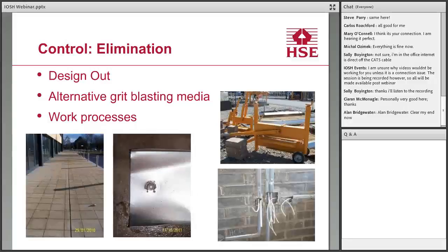In the middle is shot firing. That's an alternative to drilling. On the right-hand side is a block splitter, so that takes away the need for using cut-off saws. It's quick, there's no noise, there's no vibration, there's no dust, so it's a really simple solution. And in the bottom right-hand corner is an example of where they haven't chased out. What they've done is overcovered the cables prior to boarding, and all they've had to chase out is the back boxes. So they've significantly eliminated the amount of dusty tasks. Those are types of practical things that can be done.